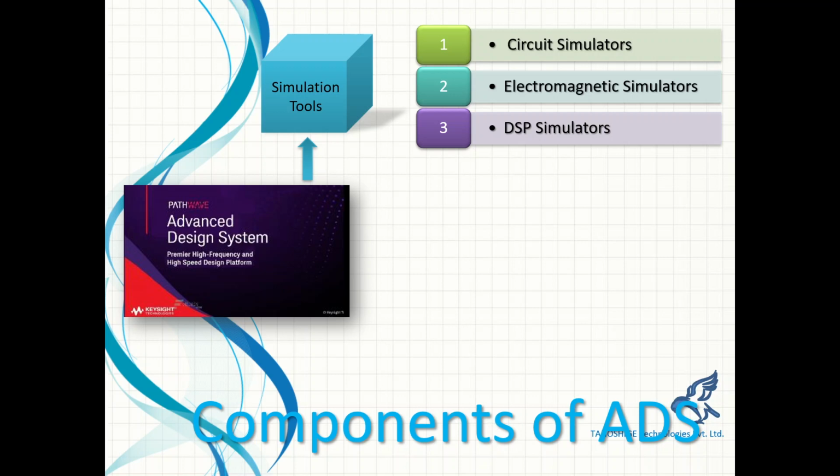Then there are simulation tools, like for example you can do a method of moment, right, which is a 2.5D. So even your metals can have certain thicknesses, right? But the 3D entry tool is not there. It is a 2D entry tool. So you have a Z profile, but then all your drawings are on the different layers of metals, right? So you can do a planar design very easily in this 2D entry tool, much easier than what you can do in 3D entry tools, right? And then you will be able to export this also to 3D, full 3D entry tool, like for example EMPro.